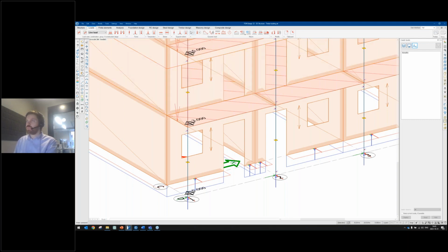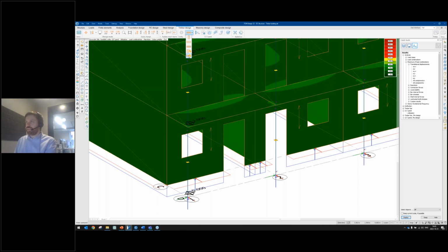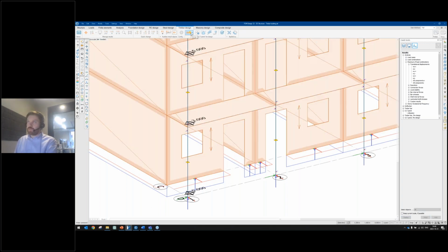When we define this, we are able to go into the fire design. If we go over here and select the CLT panel fire design, we also have fire design for bars, but in this case, I'm limiting myself to showing just the CLT. And all the buttons following this selector will change. So in this case, we have different calculation parameters for the fire check.